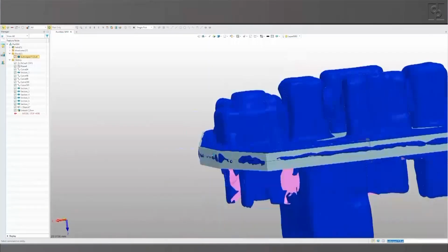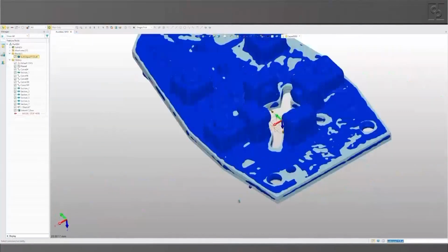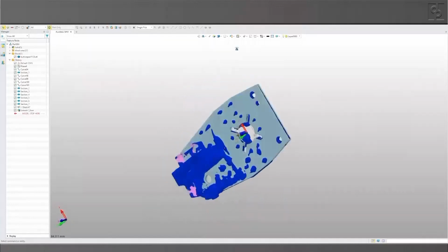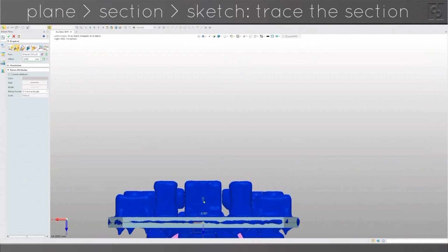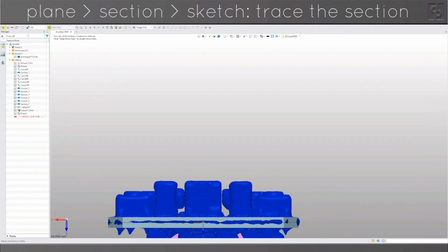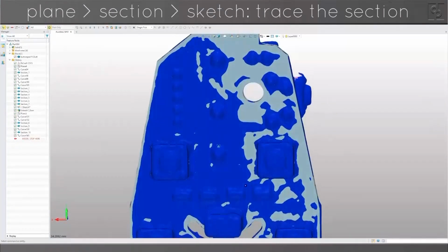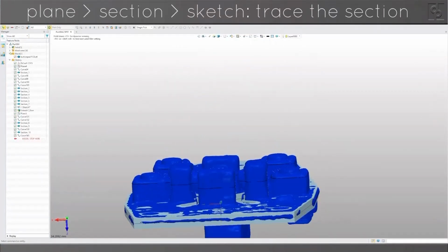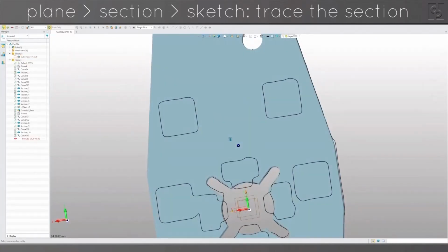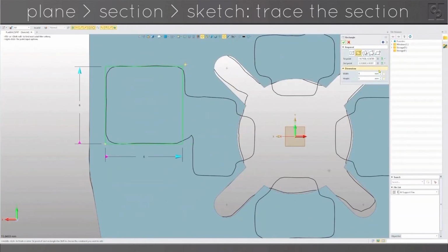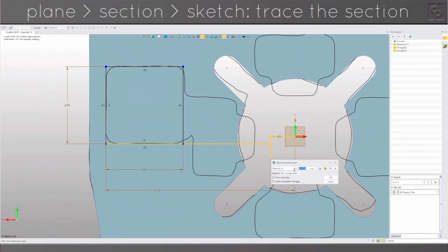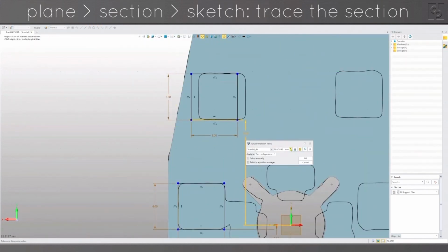For the remaining elements of my PCB packaging model, which is the components on the PCB, after extruding my first sketch, of course, to make the board itself, I'm creating a plane and cutting a section through the scan on the plane, hiding the scan, and then creating a sketch on that plane and tracing over the scan sections and approximating them to make them neat. So there's the first switch, which I happen to know from the reference manual is 6 by 6 millimeters.